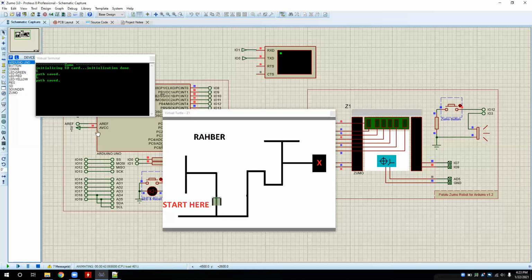So you can see that it takes a left turn, path saved L, again a left turn, L is saved. Now again a left turn, now it has turned back, so path B is saved. S is saved when there are two options, left or straight: the bot will take the turn first, and when nothing is found in front of it, it will take the straight path like this. Here the bot will go straight.